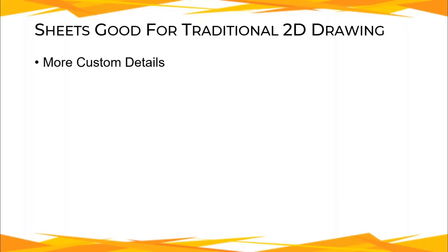But some of the more custom details that aren't necessarily modeled in the OBM model, I mean, they could be if you wanted to take the time and if it was worth the effort of doing it, but in most cases, they're not. So we're talking like steel girder elevations, although Bentley did just introduce a new feature where they can kind of automatically create steel girder elevations based on the model, and it actually is that flattened out, unraveled view that we need and are used to in steel girder elevations. But I wouldn't say it's ready for the big times yet, so it's not turned on in our workspace yet.